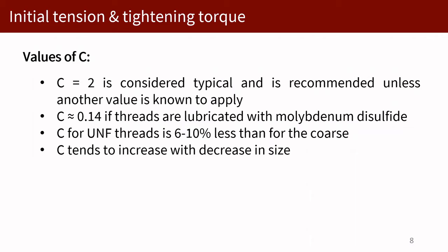So from the experience of designers and engineers, it is said that the torque coefficient tends to increase with decrease in size. So if there is a significant difference in size, it is imperative that you use a lower value of the torque coefficient.